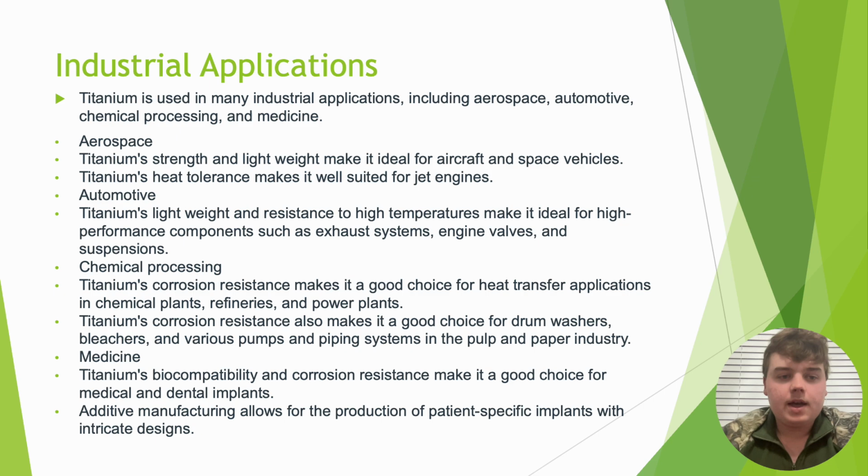Chemical processing. Titanium's corrosion resistance makes it a good choice for heat transfer applications in chemical plants, refineries, and power plants. Titanium's corrosion resistance also makes it a good choice for drum washers, bleachers, and various pumps and piping systems in the pulp and paper industry. Medicine. Titanium's biocompatibility and corrosion resistance make it a good choice for medical and dental implants. Additive manufacturing allows for the production of patient-specific implants with intricate designs.